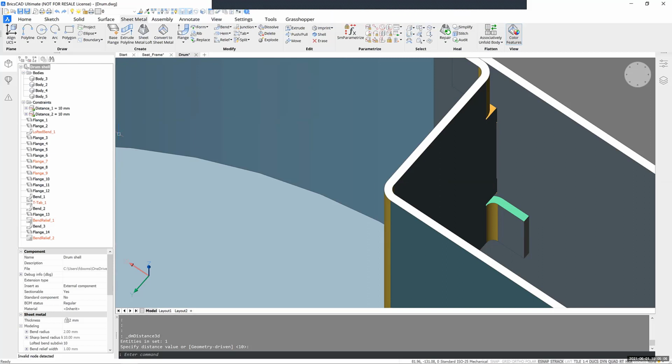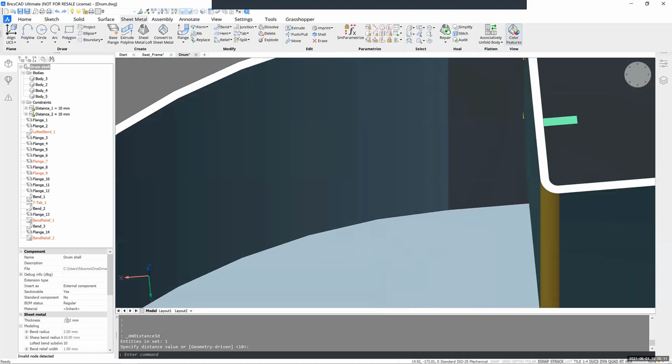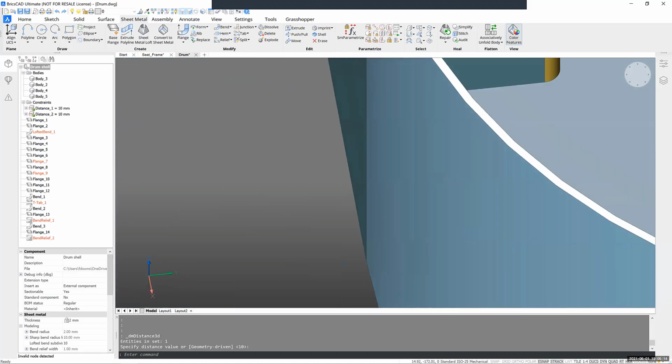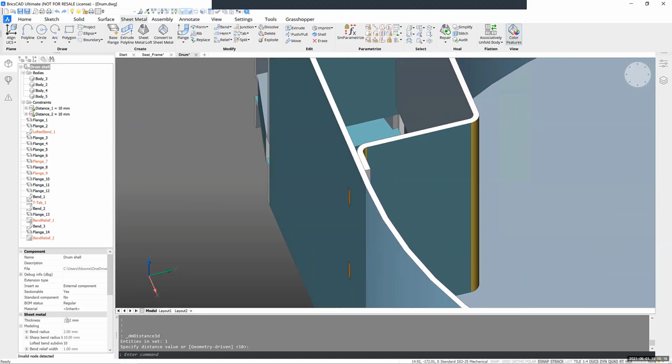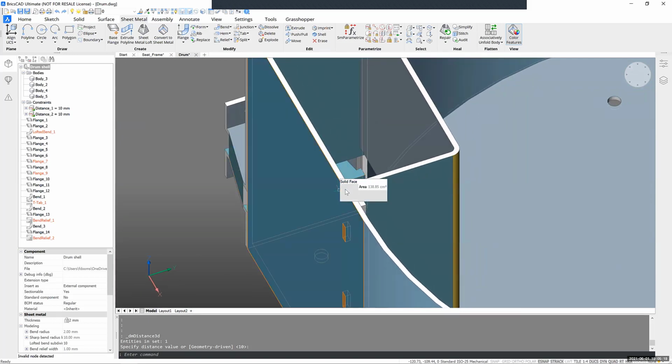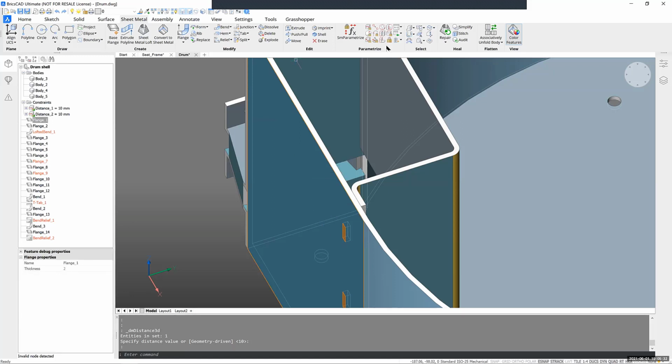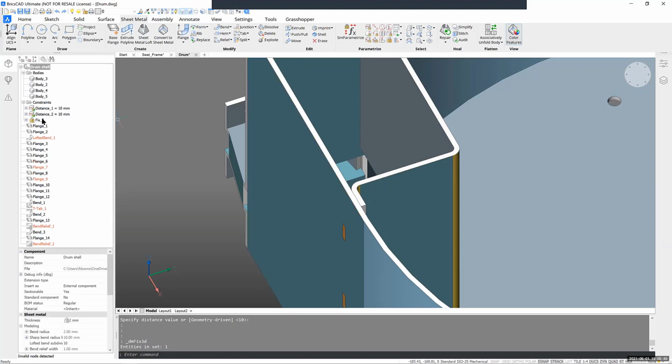Then the next thing I want to do is just make sure there is one fixed element. The constraint engine always works best if there is one fixed element which doesn't move, places where you kind of start your parameterization from. And that is, in this case, this outer face with the tabs in. I just click it, and then I fix it in place with this lock icon. And then you should see also this fixed constraint appearing in your mechanical browser.